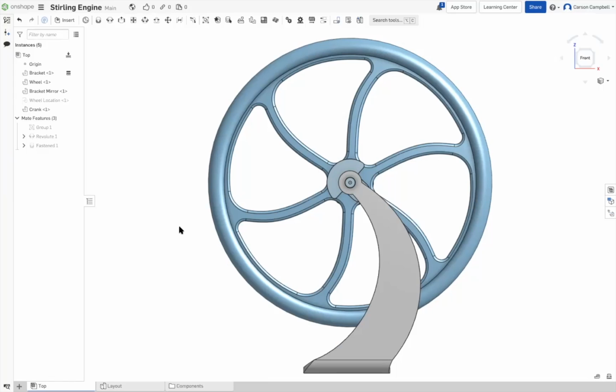I think the rule of thumb is that once a part is inside an assembly, it stays put and doesn't update. But it is updating. The location of the crank in the layout rotates. When we go back to the assembly, it's rotating in that assembly too. So these are things that we have to be mindful of. Go ahead, rotate the wheel here.